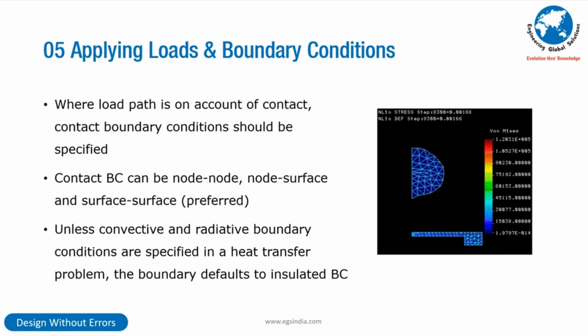Initial boundary condition could even be energy. You look at this example of an extreme deformation taking place in a jelly. What you are seeing over here is the initial boundary condition being potential energy. When you drop an object, you just drop it in free-falling gravity. Does it have an initial displacement, initial velocity, initial acceleration? No. What does it have? It has initial energy. So if you give initial acceleration, initial velocity, initial displacement, it is wrong. You have to give the potential energy and allow it to go for a free fall with gravity turned on. Otherwise, your deformation is not going to be correct.